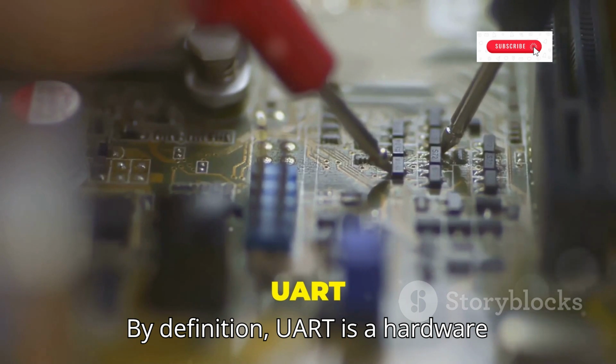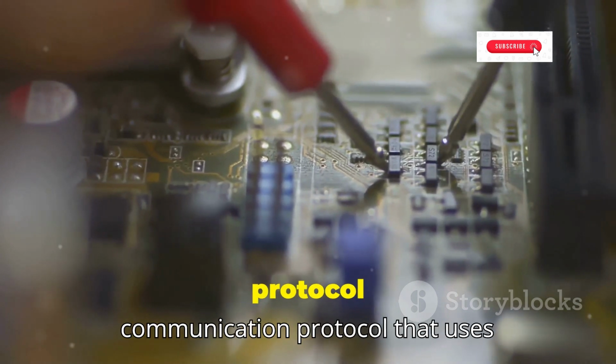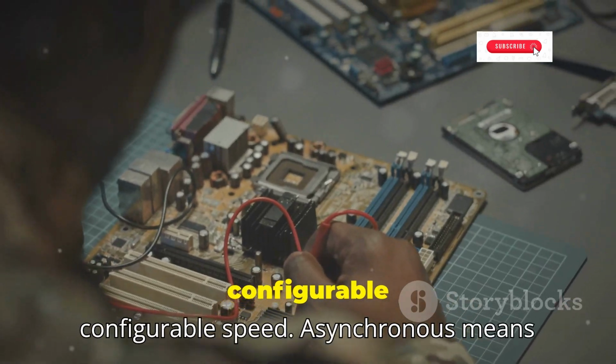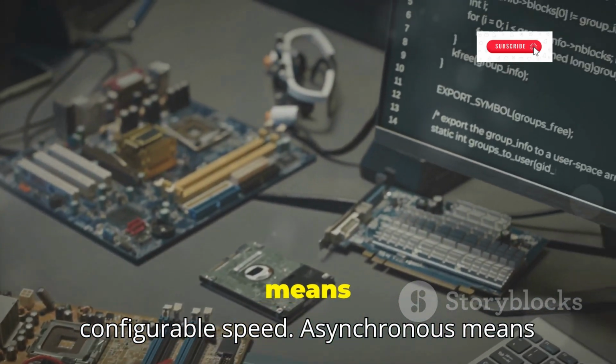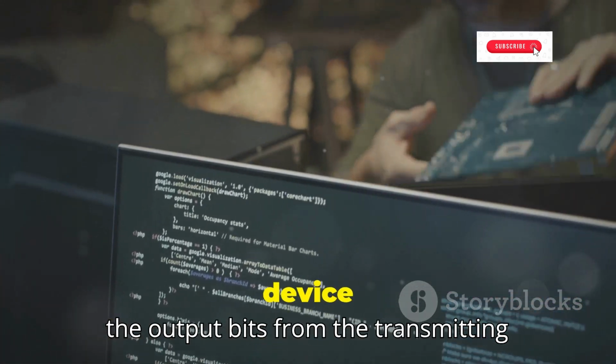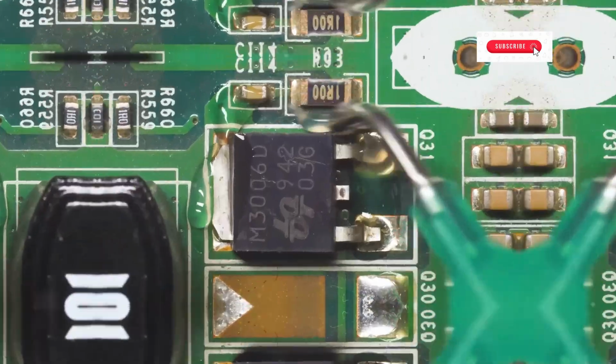By definition, UART is a hardware communication protocol that uses asynchronous serial communication with configurable speed. Asynchronous means there is no clock signal to synchronize the output bits from the transmitting device going to the receiving end.